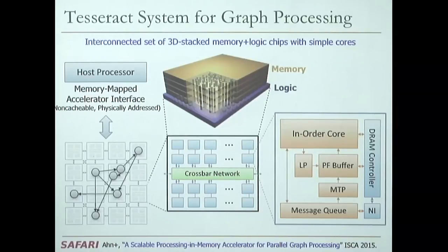In-order means in-order processing. Why do we not have out-of-order cores? Because that probably generates a lot of heat. And one of the problems, as we've discussed in this kind of architecture, is heat has nowhere to really escape, right? Because you generate heat, and it goes up, but then there's memory layers up. It doesn't get consumed through the air.